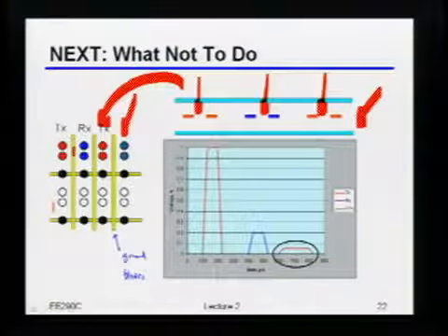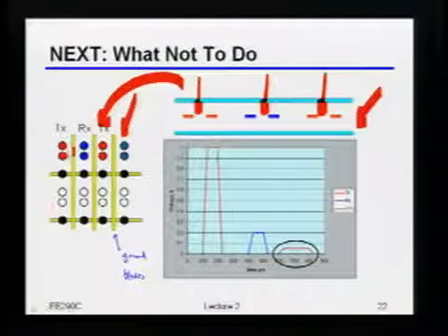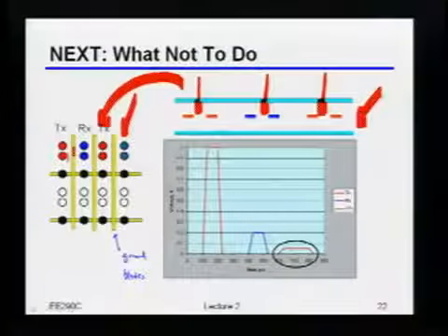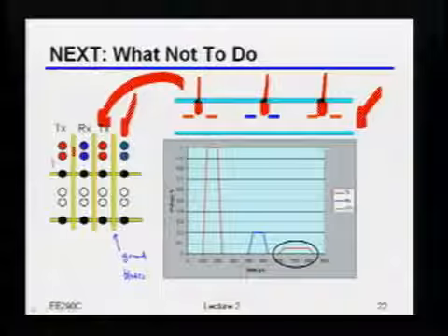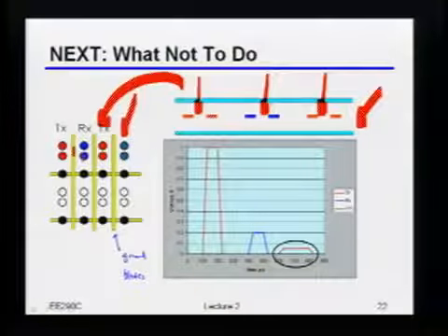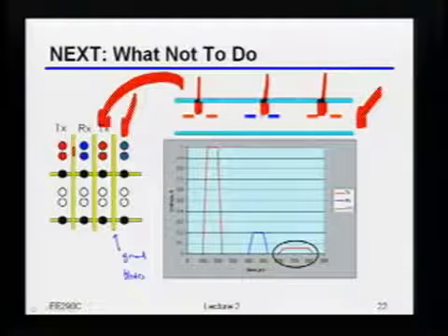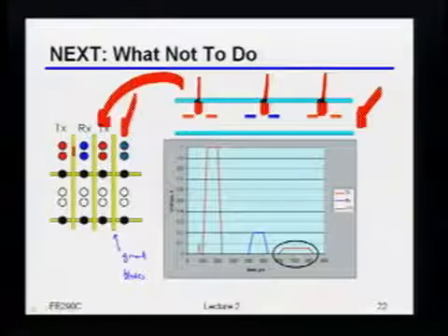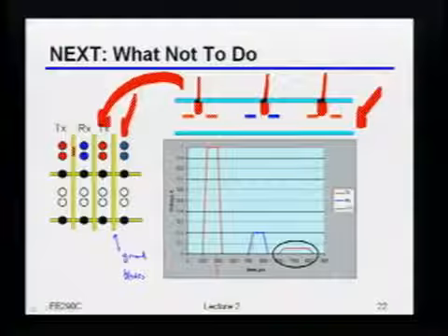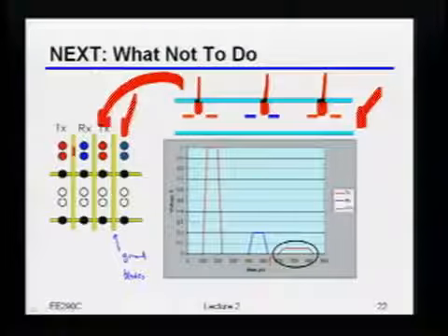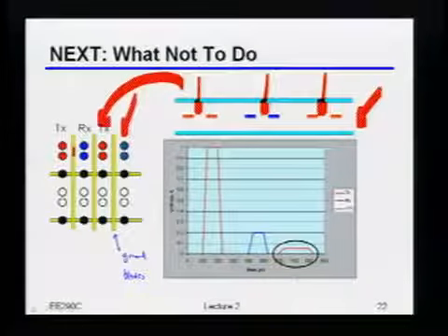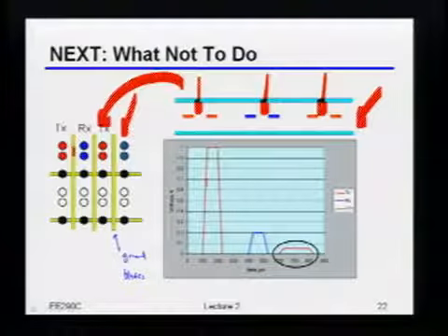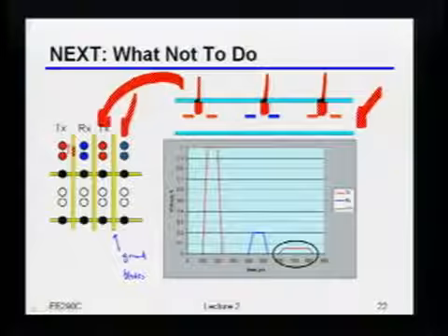So that means that once I hit this point, A, I'm going to get some discontinuity, and then B, I'm going to get some coupling, because that discontinuity is going to flow back through the receiver over here. As an example, if this is what I transmitted, and this would be the received signal that I would have gotten, this thing over here is the near-end crosstalk that I would pick up from the transmitter, just due to the discontinuity that I hit at that connector point.